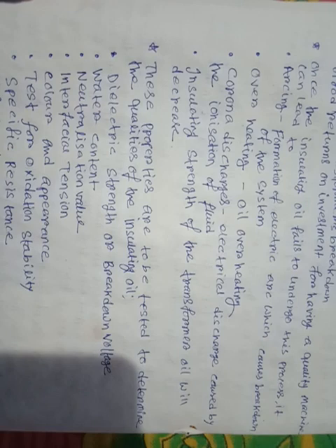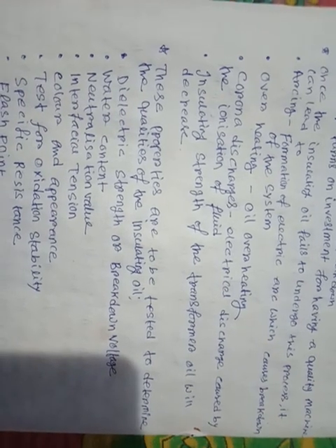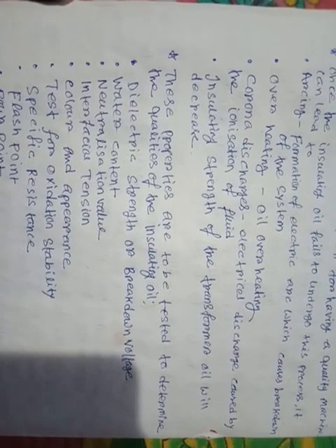When the breakdown strength or dielectric strength decreases, at this time the transformer can have a breakdown. Second is water content. We'll test the water content of a transformer oil.